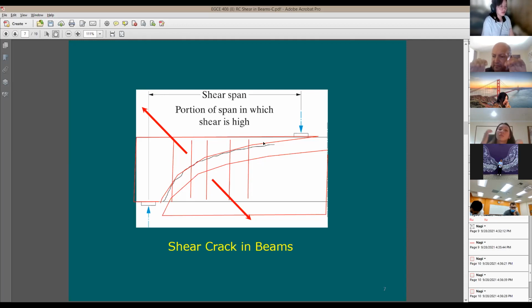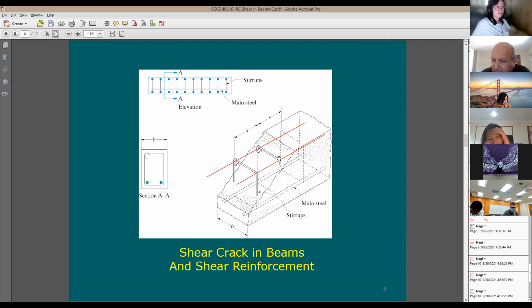Just to bring it back together, to keep it in one place. It's exactly what you're doing, but instead you're doing it with steel ties, because here you're talking about concrete. In a case like this, what's really bringing the strength is going to be the vertical leg. You see, the vertical leg of the tie is what's causing the strength, as long as it is hooked around the top bars and the bottom bars.